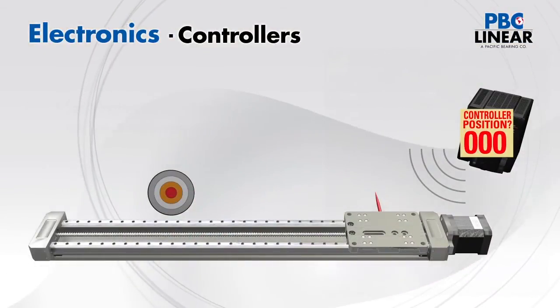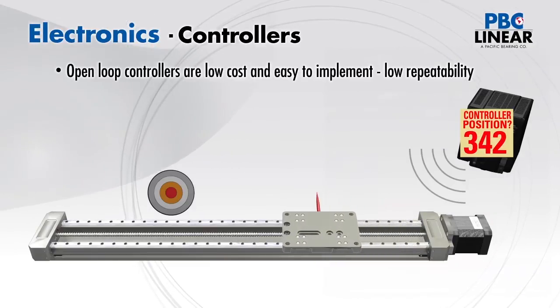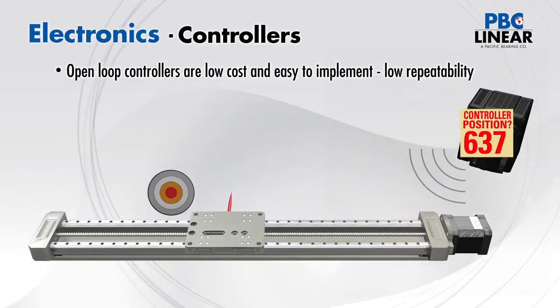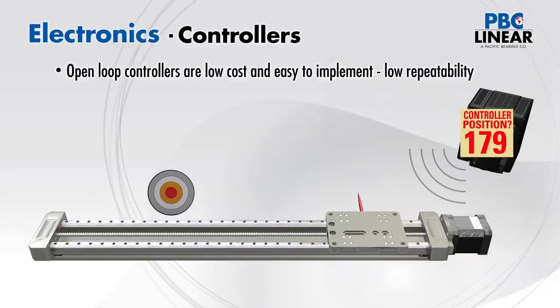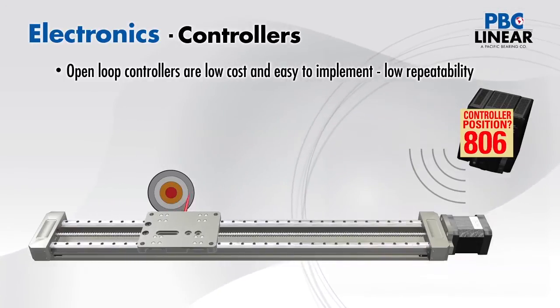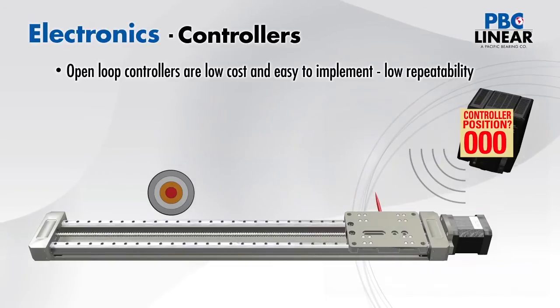Another thing to consider is how the position is to be measured. Open loop or non-feedback controllers, when used with stepper motors, are low cost, easy to implement, and can be very accurate. However, the controller assumes that the position of the point of interest sent to the motor is reached, when in reality a motor stall or jam could cause the system to lose repeatable positioning.